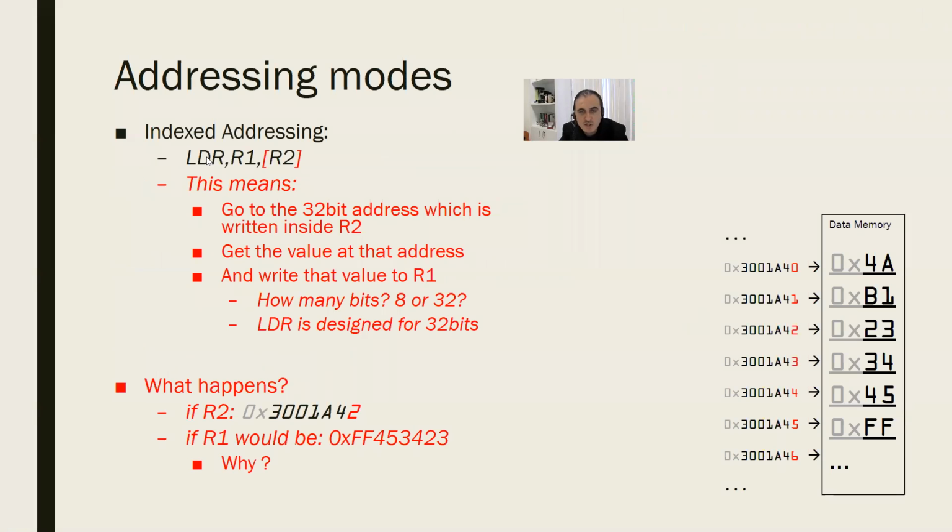And if the instruction was, for example, 32 bits, since 32 bits were made of 4 different 8 bits, 4 times 8 equals 32. Since LDR is by definition a 32-bit, in other words, 4-byte operation, I read the number starting from this address, counting 4 cells in a little endian manner. What was the little endian manner? Lowest address will be the least significant byte.